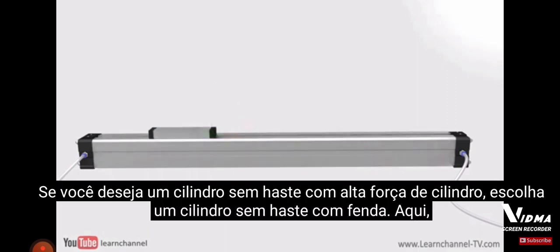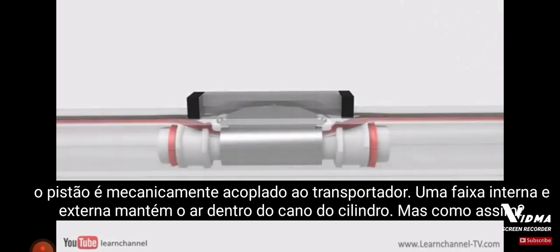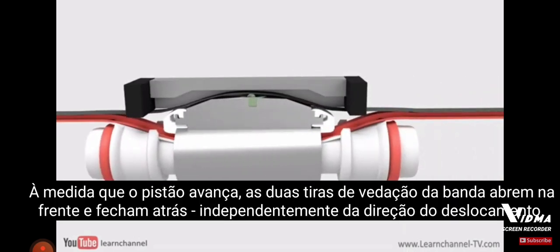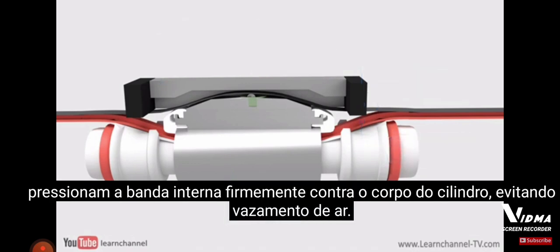If you want a rodless cylinder with a high cylinder force, you would choose a slotted rodless cylinder. Here, the piston is mechanically coupled to the carrier. An inner and outer band keeps the air within the barrel of the cylinder. But how so? As the piston drives, the two-band sealing strips open in front and then close behind, regardless of the direction of travel. The seals of the piston inside the cylinder barrel press the inner band tightly against the barrel of the cylinder, preventing air leakage.